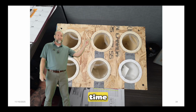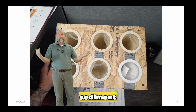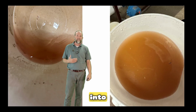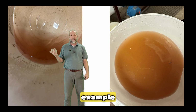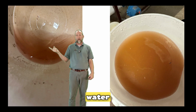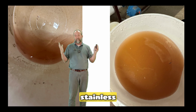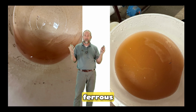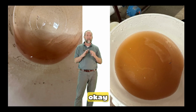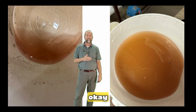And you can see over time, and we're going to look at a few more bag filters, the stuff that gets removed, the scale, the sediment, everything that's coming out of the system due to adding the nanobubbles into the system. Here's another example of some blowdown water. This is what you can expect to get out of your blowdown water in any type of system that might have galvanized pipe or stainless steel pipe or any sort of ferrous metal pipe. You may get some orange water that looks like this in the beginning. This is the worst case scenario. This is not how it always happens.